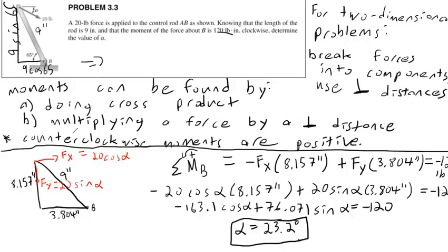Tell me again why y is positive. You look at that force diagram and you see y going down. Are you okay with that, y is going down? So okay, the question is, show me again why the moment generated by Fy is positive. And the reason for that is, are you okay that Fy is going downward? You okay with that? Yes. Okay. And so you look at this and say, this is clearly causing a counterclockwise rotation about point B. Fy clearly wants to rotate counterclockwise about point B.